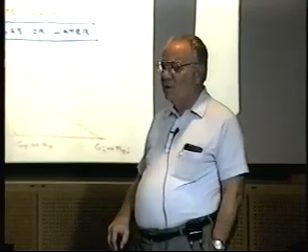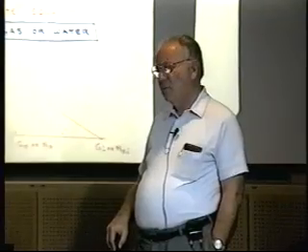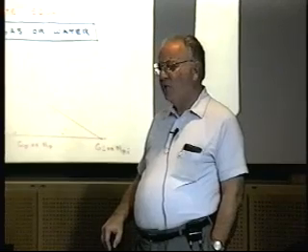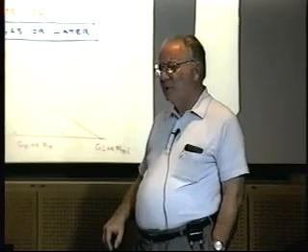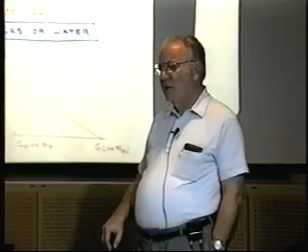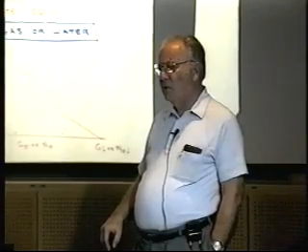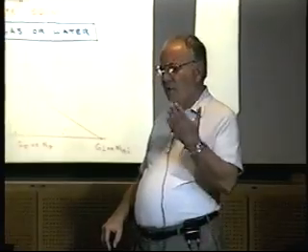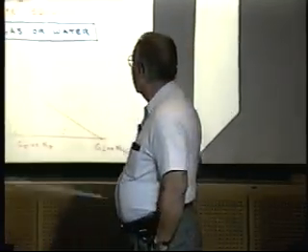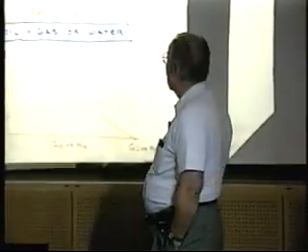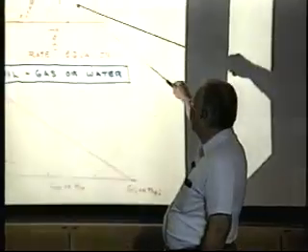Well, I don't know if we'll get to show it here now, but water flow is a function of a difference in pressure. The oil flow is a function of a difference in pressure squared. So there's a different amount of water that you're going to get with respect to oil for a change in flowing pressure, and you have to understand the difference in flow equations: delta P versus delta P squared.